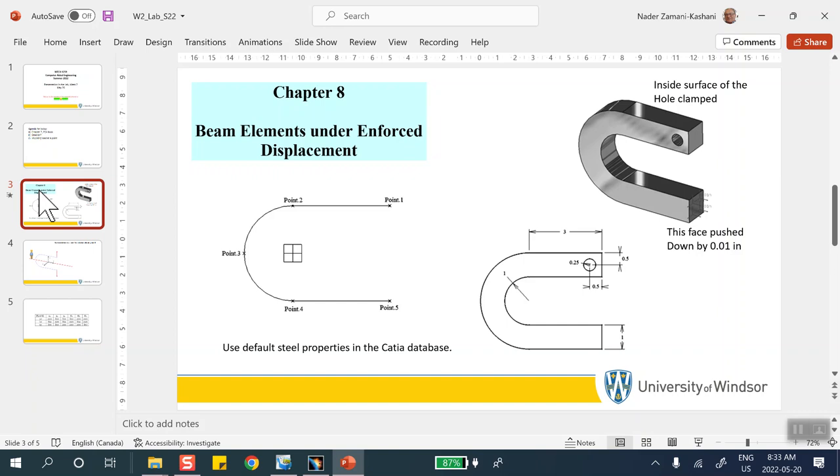Now, that does not mean that beam elements are useless, okay? In many situations, you may not be interested in the stress in the beam, but you want to make sure that beams support other things, such as this safety glass. Like what we may be interested in is the shield itself, and these are supports. We just have to make sure that they're reinforced properly, etc. Hopefully, this was designed so that it carries that weight, etc. So we are not necessarily interested in the stresses in this, but we are interested in the stresses in this or the bottom, the legs, etc. It doesn't mean it's useless.